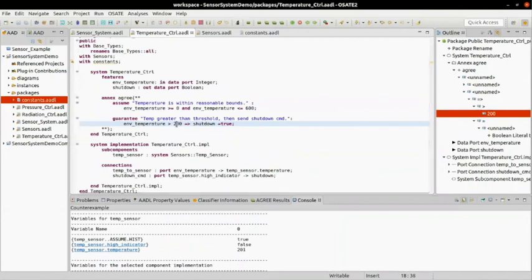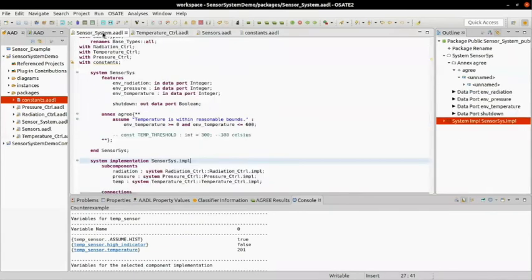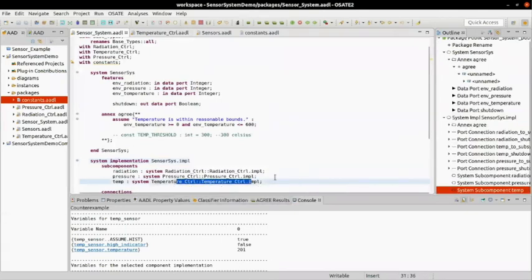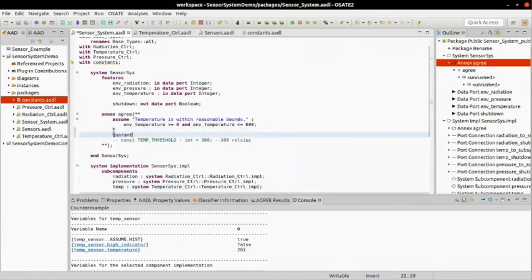We'll put this in correctly. And then we move up a level. So now I know that with this, everything proves. So now I can move up to the parent level. Now at the parent, I'm looking at just a slice of that architecture. So I have the top level, and I use just its direct child to prove that guarantee. So it's only going to use the temperature subsystem. It's not going to reach all the way down into the sensor. Nonetheless, I want to write a guarantee.